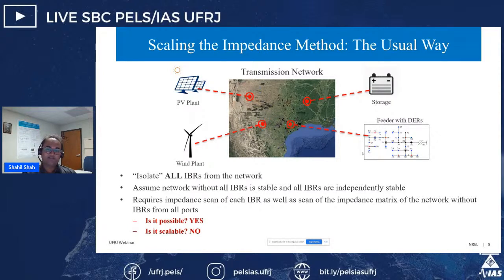And as power system engineers, we know that any three-phase port or three-phase network, its impedance is actually not one-dimensional, it is two-dimensional. If we define it in dq, then d and q are going to be two axes, so you have to consider the full dq matrix with four elements. If you use positive sequence, negative sequence, we still need to consider coupling. If you use phasor domain, where we consider magnitude and phase of a quantity, there also you have to consider coupling between magnitude and phase. But my point is that from each port, the impedance will be 2 cross 2.